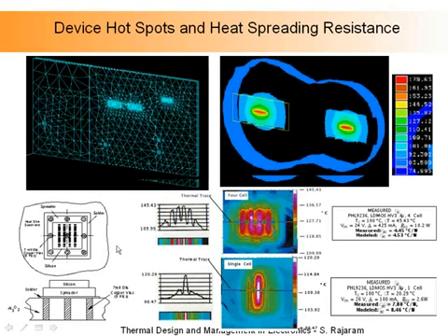And what we've done here is we've actually opened the device, removed the cap, and we've measured the temperatures using an infrared. So this particular device has 4 fingers dissipating heat, and that's these 4 fingers of hot red that you see. And this one has a single finger that's dissipating heat, and that is, when you take the infrared picture, this is a single picture of it.